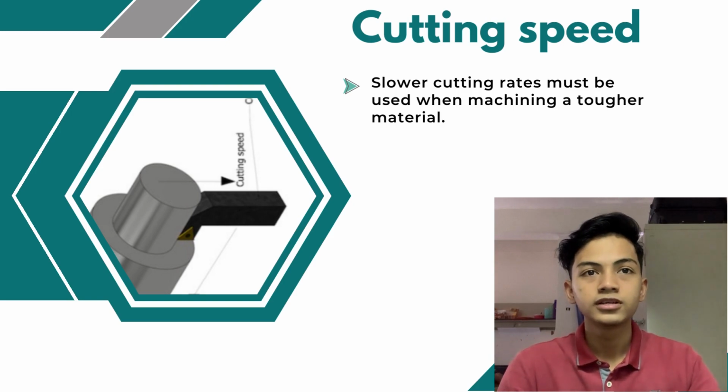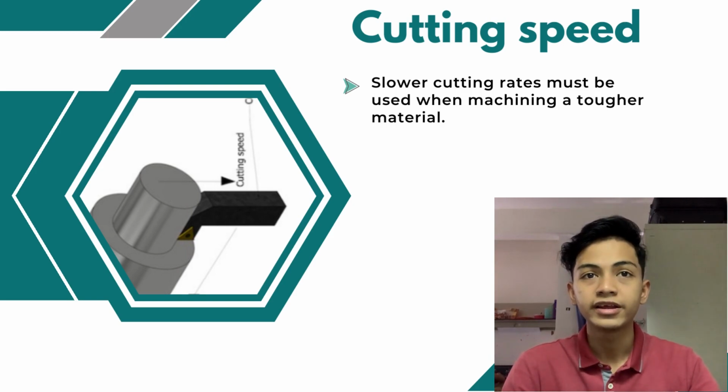The most important cutting parameter for providing the required cutting motion, it can be applied to the cutting tool or the workpiece by rotating or reciprocating it. In the event of a rotating tool, such as milling, drilling or grinding, or a rotating workpiece such as turning, the cutting speed is determined by the peripheral velocity of the cutter or workpiece.